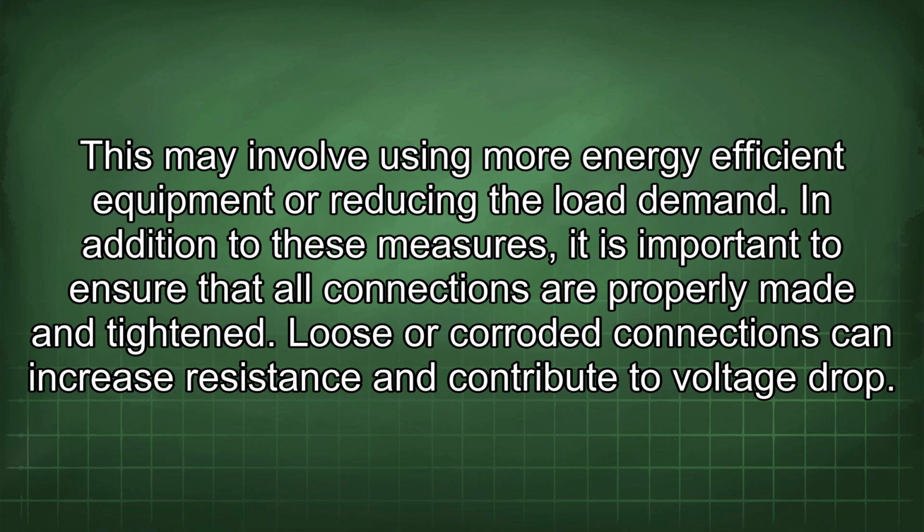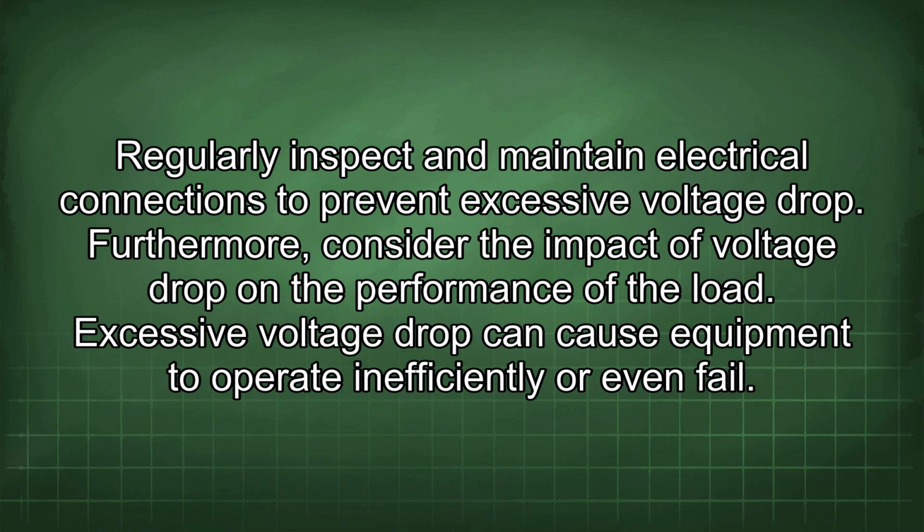In addition to these measures, it is important to ensure that all connections are properly made and tightened. Loose or corroded connections can increase resistance and contribute to voltage drop. Regularly inspect and maintain electrical connections to prevent excessive voltage drop.